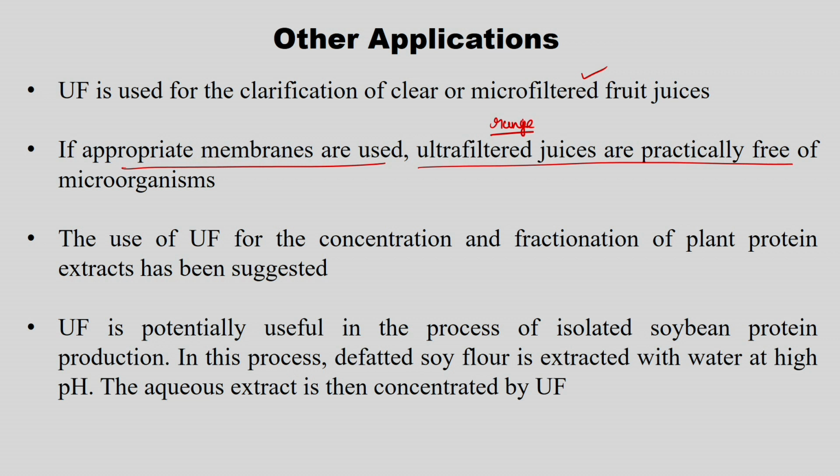The pore size range I choose should be able to retain the microorganisms. If that is the case, we call it cold pasteurization or cold sterilization, without applying thermal processing. The use of ultrafiltration for the concentration and fractionation of plant protein extracts is also suggested. We use ultrafiltration membranes to concentrate and fractionate plant protein.